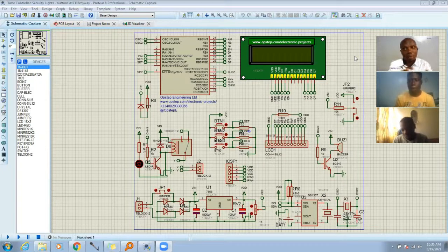Now, this is how it happens on the microcontroller too. On the microcontroller, if you do not save any information, maybe a RAM content, a register content, if you don't save it in the external EEPROM, those are the 24C series, those ones are from Atmel, the serial EEPROM, or the internal EEPROM of the microcontroller, if the microcontroller goes off, it doesn't remember that information again. It has to start all over again.